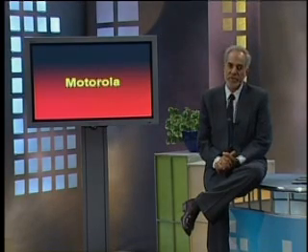But at what cost? The cost is a longer duration of evaluating and executing different instructions. Some instructions might be executed, for example, in fewer clock cycles, and some other instructions might require a much longer number of clocks. Now, how many clocks are required, and this complete data is available to you in the form of tables from the manufacturer, depending upon which family of Motorola you are using. In most of the desktop machines, it is the RISC processor which is used.